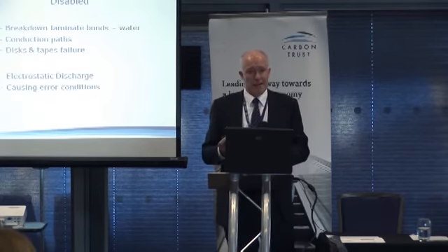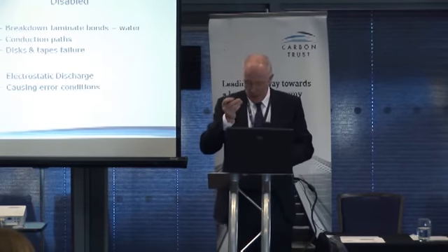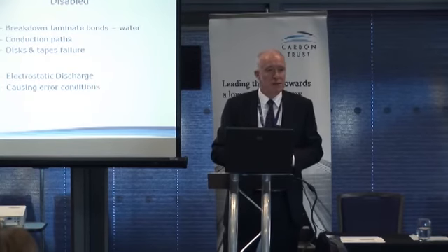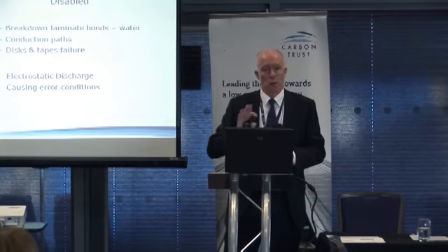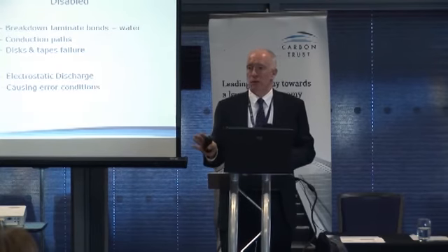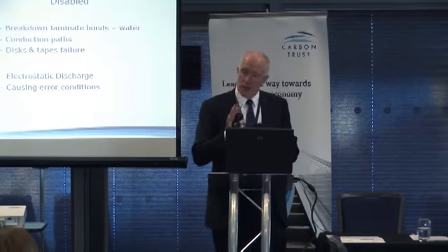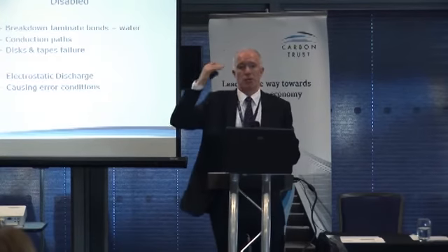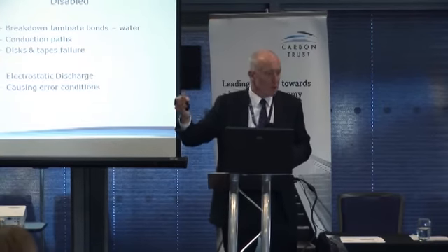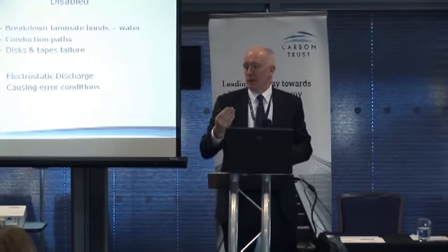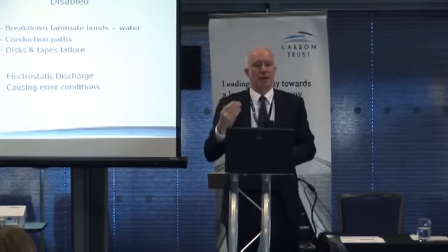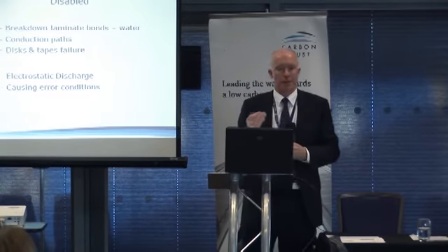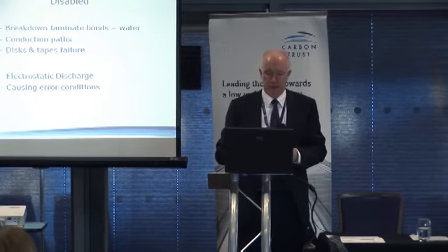In practice, and I think the point's already been raised actually, lots of network server hubs sit in small businesses on the floor of offices, quite happily trundling away without temperature control, without humidity control, and without any failures. So you don't necessarily need to air condition at all. When you need to air condition is where you rack these up, when you stick a number of servers on top of each other, each generating a few hundred watts, and you start to become an electrical heater because you're generating kilowatts in a rack. You put kilowatts in a cabinet, it's going to get very warm and damage your kit. So that's why we sometimes have to air condition our data centers, because of that rack.